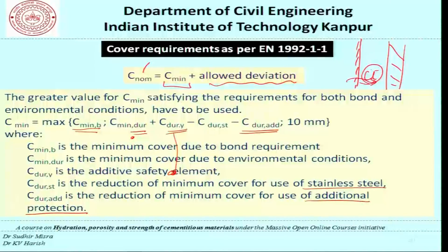So, the chloride attack in this case is not only being addressed by the concrete here, but also by providing an impervious coating or using a certain special type of formwork and so on. So, indeed it stands to reason that this cover requirement can be revisited and in fact reduced. So, that is what is being allowed here by adding this term